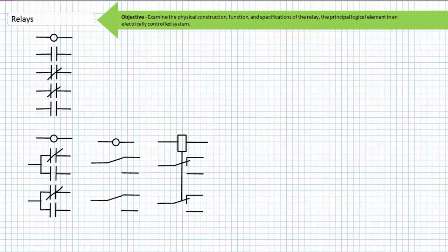The IEC terminal numbering scheme uses 2 digits. The first digit is the specific switch. For this schematic symbol of an industrial mini-contactor relay with 4 electrically isolated switches, 2 of them being normally open and 2 of them being normally closed, this is the first switch. Each terminal of this specific switch is assigned the first digit of 1.